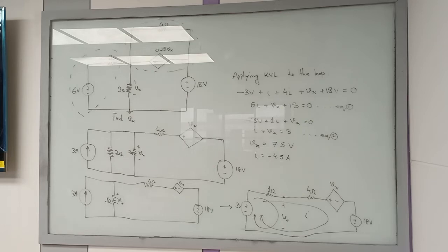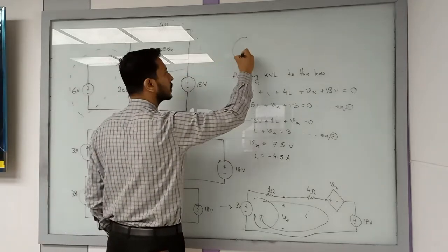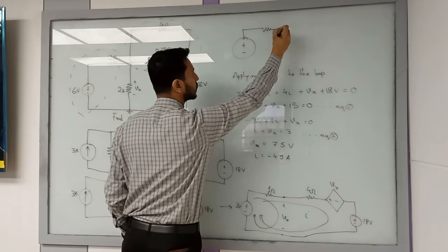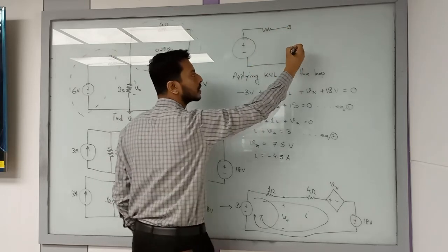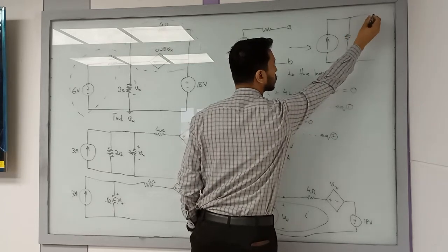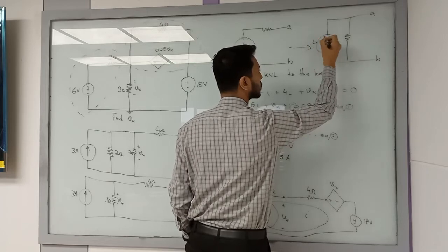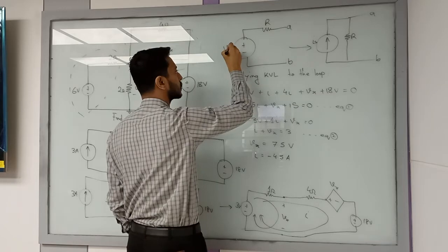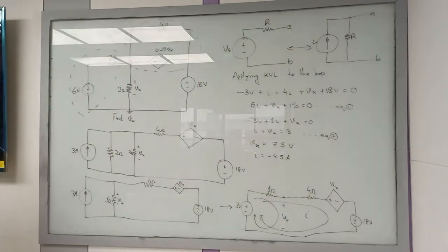So basically you need to follow one rule and you need to apply the basic rules. Okay? So the main rule is you can convert a voltage source and a series resistor to a current source with a parallel resistor. So this is vice versa. So you just need to remember this portion. Then you can form a simple circuit from a complex one using this source transformation and find the unknown parameters as well. Okay?